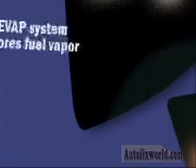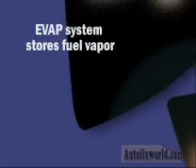The purpose of the EVAP system is to capture and store fuel tank vapors instead of venting them to the atmosphere. Since fuel vapor leaks are a major cause of hydrocarbon emissions, vehicle fuel containment systems are now tested for leaks by an enhanced OBD2 monitor. A failure in the EVAP system can store a DTC and trigger the MIL, causing the vehicle to fail an OBD2 emissions test.